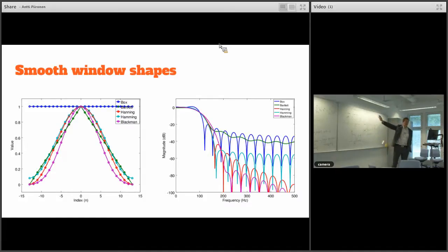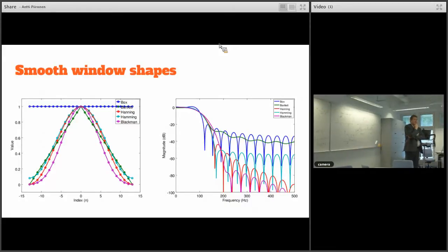So this is windowed. There has been a sinc and a window, and those are the attenuations. As you can see, the box is the worst. It's the easiest, but it's also the worst. Even Bartlett, which is not much of a window at all, just a triangle, you get better passband response. Then my favorite is Blackman, since it goes down like that one.